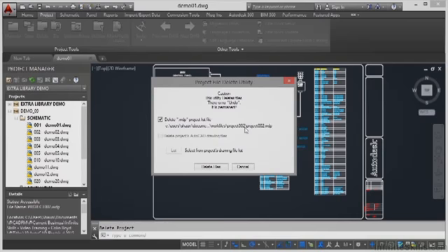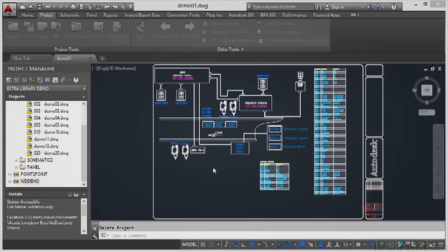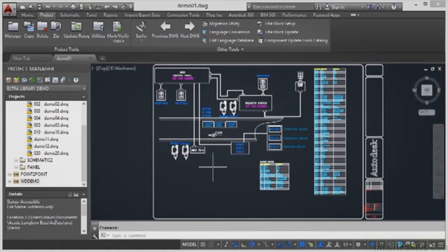Now, there's no actual drawings in this particular project. So you can see that delete projects AutoCAD drawing files is grayed out. Also list, select from the project's drawing file list, because you might only want to delete certain drawings. In this case, there aren't any drawings. So we can just delete the WDP file and we're done. So I click on delete files and that's it. It's gone. Totally and utterly gone. If I go back here, you'll see that it's gone there as well.